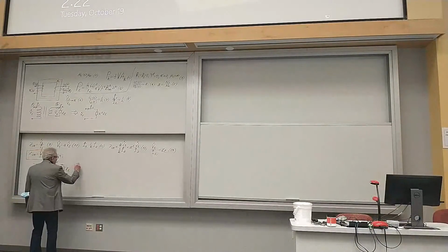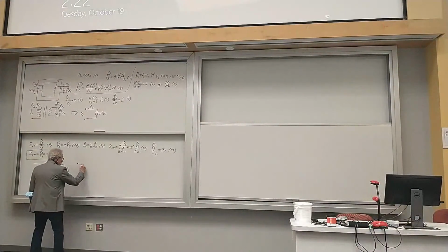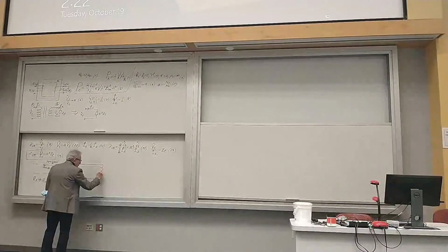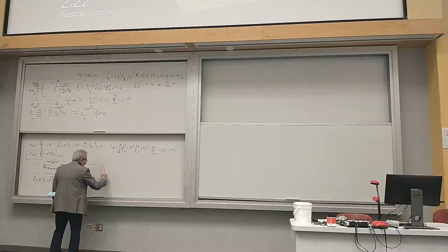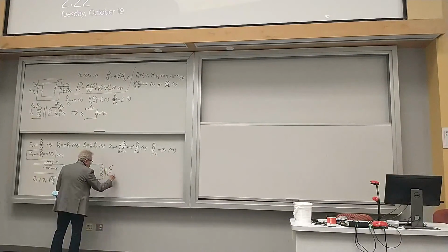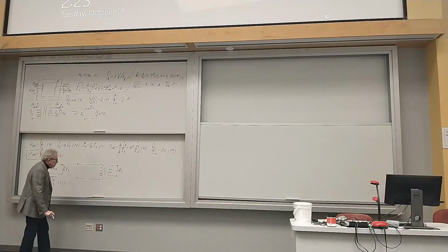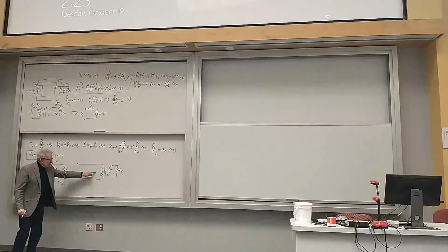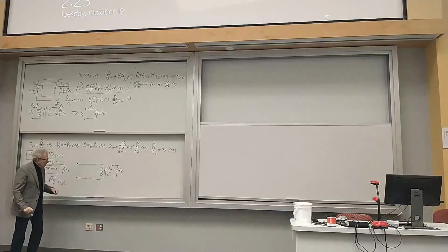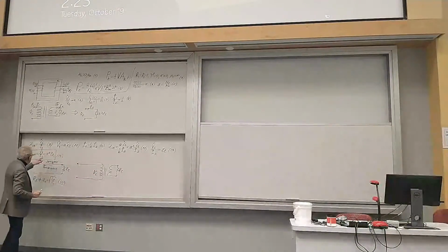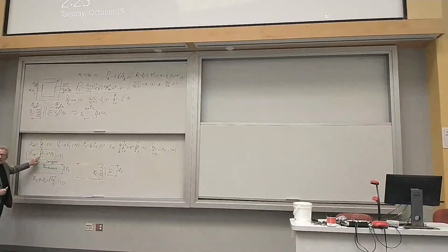Namely, if you connect the load impedance not directly to the transmission line but through the transformer, then the impedance which the transmission line will see here, R sub L prime, according to this formula, will be the input impedance of the transformer.